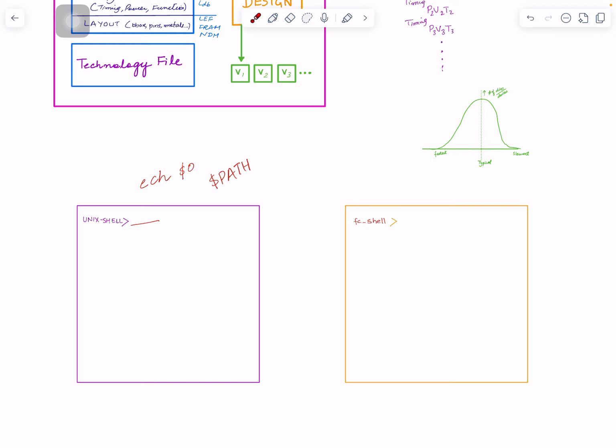This can be handy. For example, these days, on a big, huge design, you're not doing all of your physical design on just one machine. You fire jobs on different machines using a special utility, LSF, or NetBatch within Intel. So some of the variables, those child shells need to inherit.